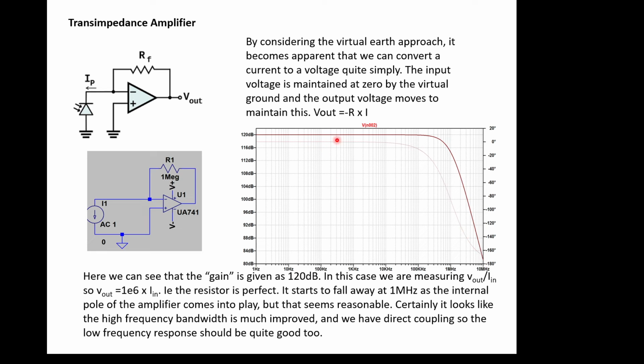And it's given us an excellent performance. And we don't care if there's a cable connecting here with capacitance, because the capacitance is shorted by the virtual ground. So that looks really good, doesn't it?